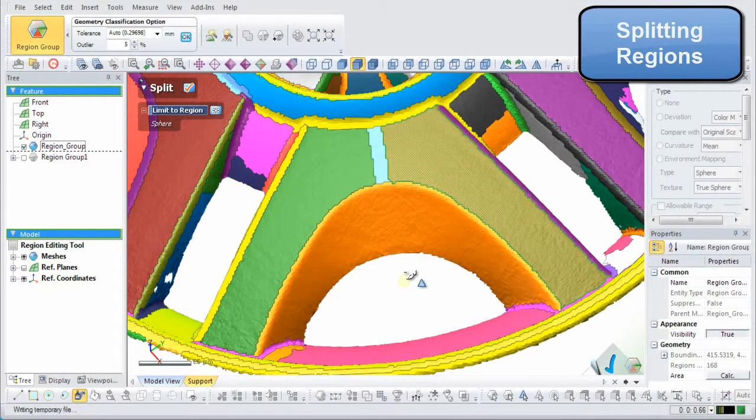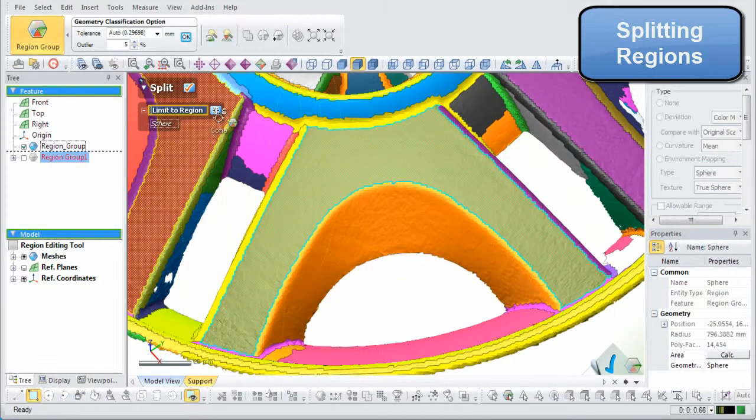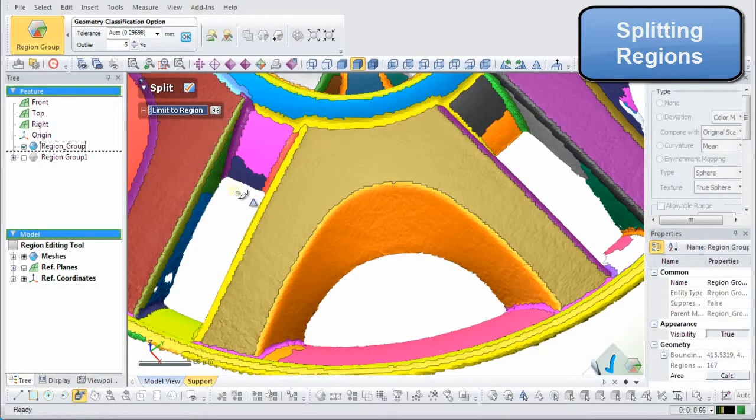In addition to the Paintbrush splitting method, polylines can now be used to split regions. Using polylines to split regions can help improve accuracy in hard-to-split areas. To use the default selection mode, click and drag, and to use a polyline in whatever mode you are in, simply click and release on the starting point, and click and release on the end point.